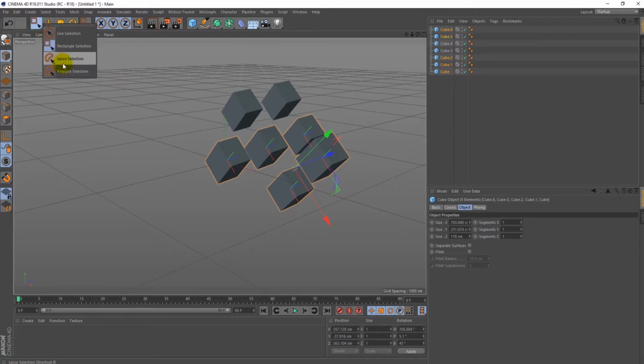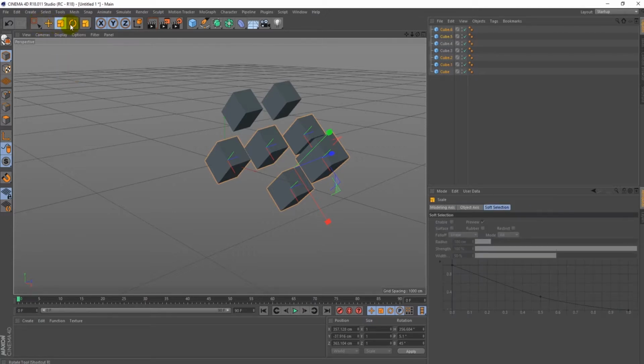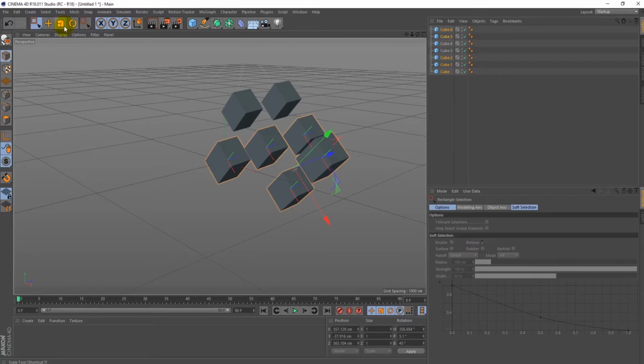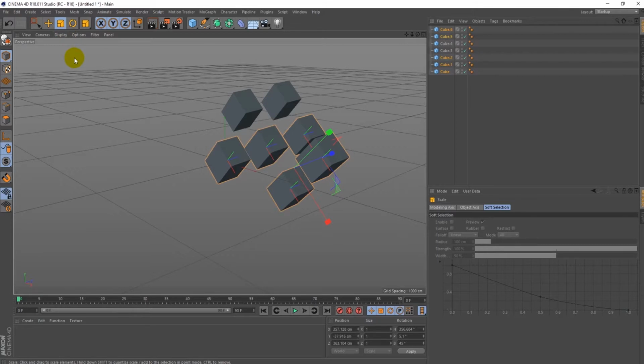There are other options that you don't need to know yet because this is just getting started. When you select the Move, Scale or Rotate tool, you can quickly switch to Selection tool by pressing space on the keyboard. Press again, it will be back.